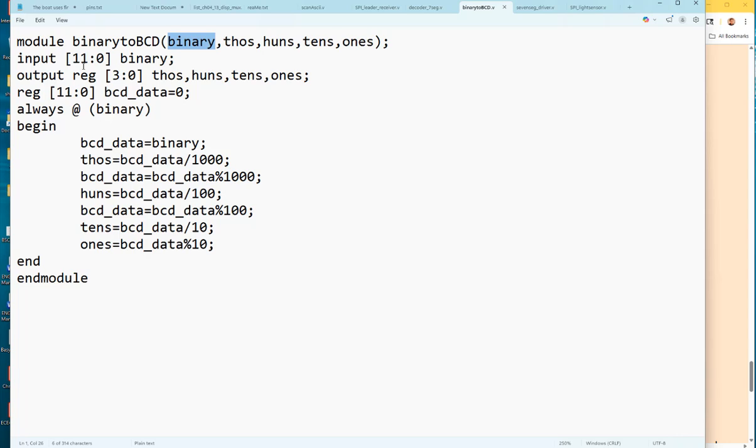So I think they designed it that way because whenever you synthesize and implement the hardware, a lot of times you are not able to change it unless you re-implement your hardware again. So it's just making it wider to be used for other ADCs, okay? But for this ADC that we are going to use for this class, for this tutorial, we do not need 12 bits. We only need 8 bits. This is one of the questions in class number 11, I think. Anyway, we don't need 12 bits. We only need 8 bits.